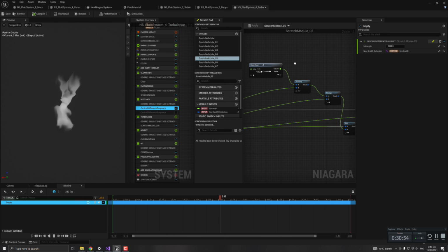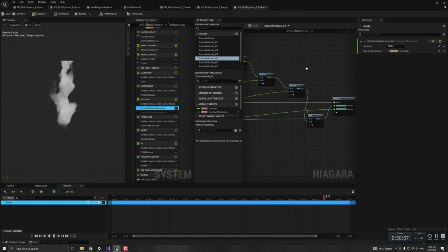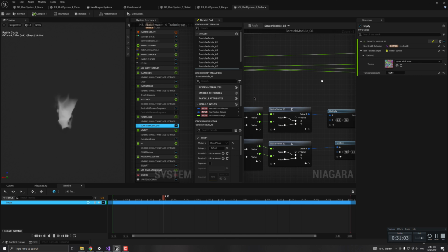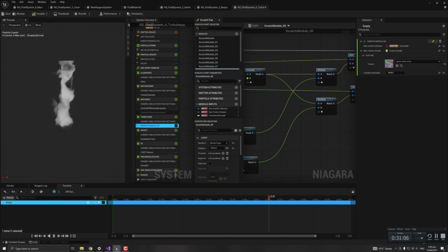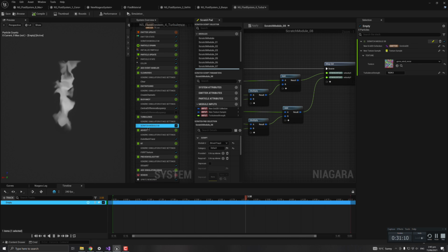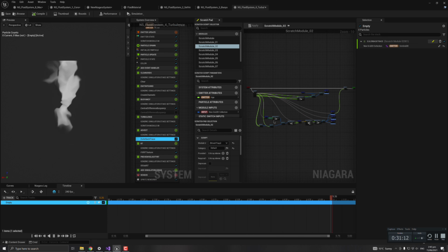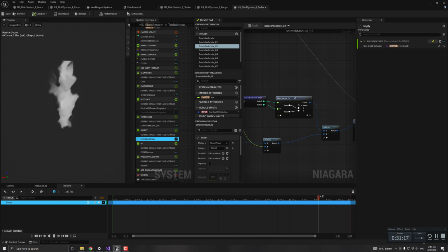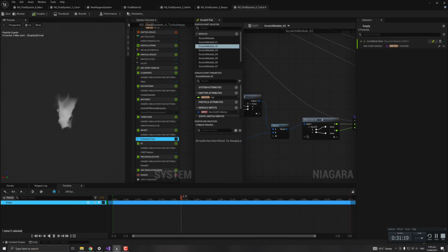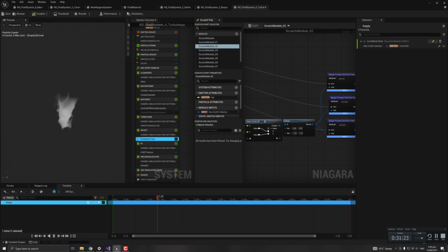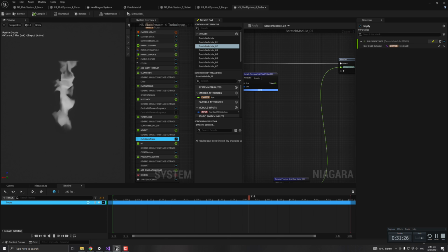Yeah, there's all this stuff here where it's just a constant value adding to the velocity, and then turbulence where we're sampling this texture again and multiplying it by dt and adding to the velocity here, and then taking that final velocity and doing advection. So the same kind of thing where we're in index space, subtract the velocity times dt, then convert to unit space, and then sample the density, and there we go.